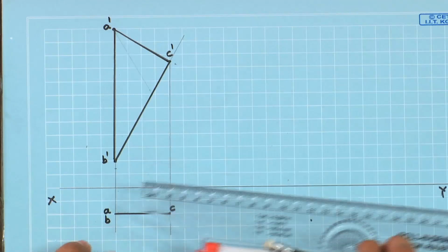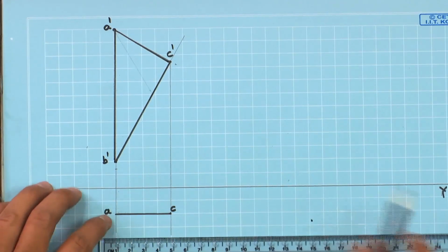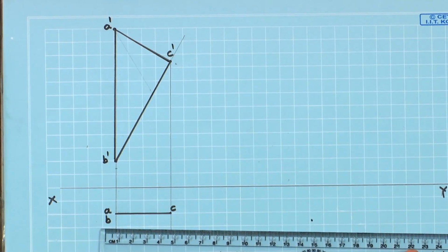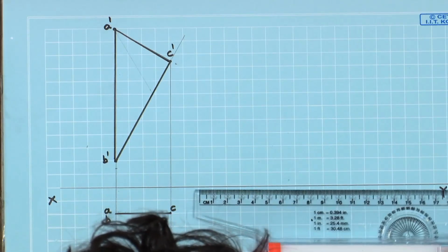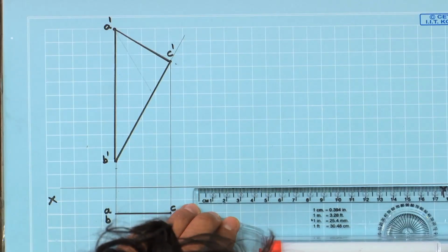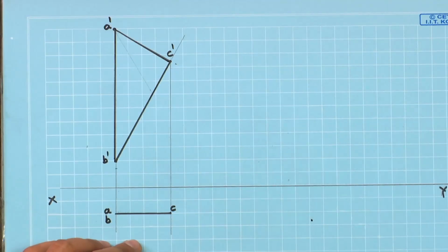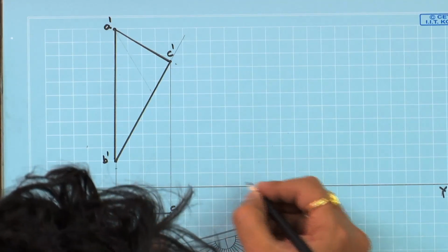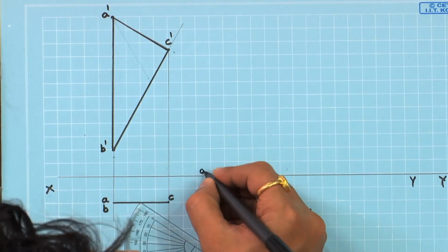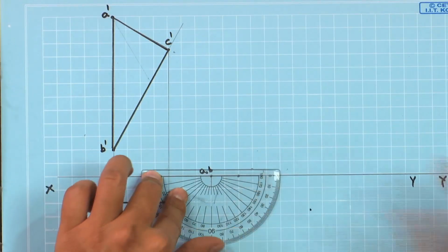Now, on the same xy plane, we want the AB line to make a 45 degree angle. So, what we can do is, on the axis itself we can construct it at 45 degrees, which this AB has to touch. So, if that is the case, pick a point here somewhere from there. So, from this point let us call AB point, it is supposed to make 45 degrees when it is in the vertical plane.